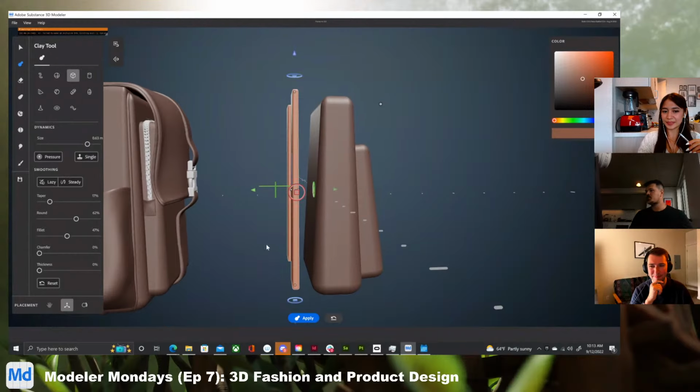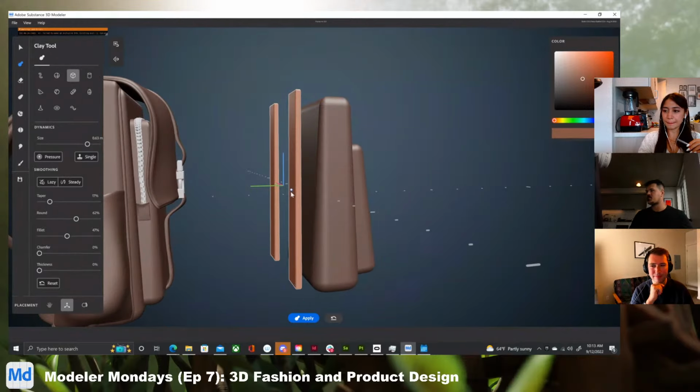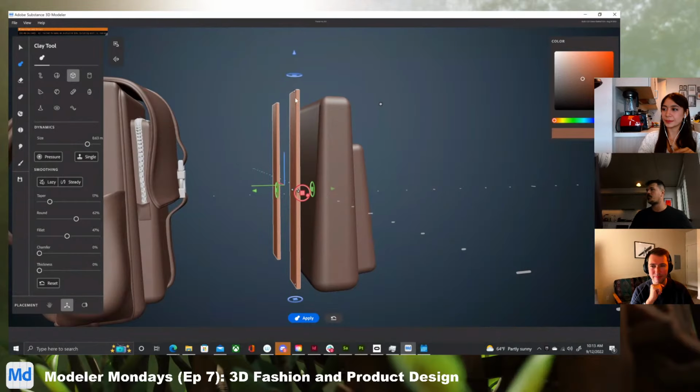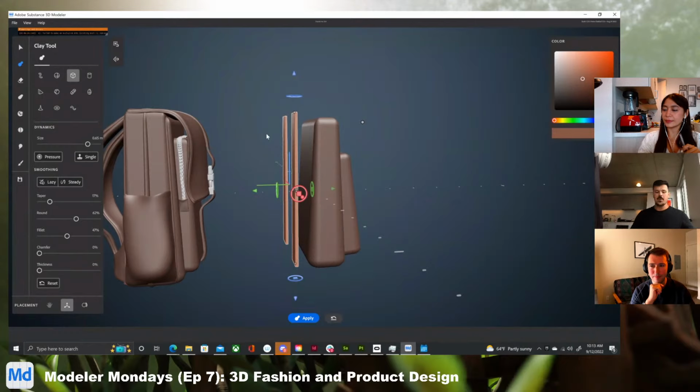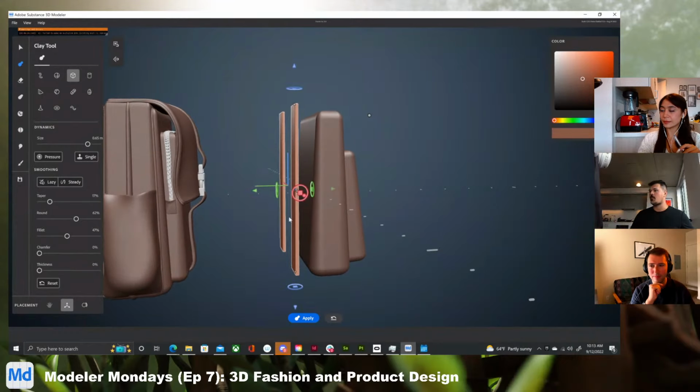And what I'm going to do, especially as I'm starting to deal with the straps of the bag, because these are going to be thinner profile, is eyeball it a bit, because I want to give a little extra clearance at the top and the bottom for that strap. So as I warp and deform it, I can do it in one singular motion. If I try to warp and deform thin surfaces multiple times in Modeler, the more I maneuver and fuss with the small surfaces, the higher chance I'm going to have holes in the model itself.